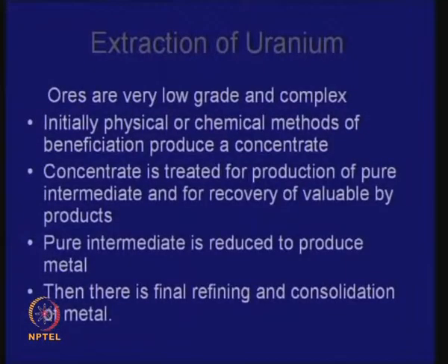We have discussed some methods for that. It could be vacuum arc melting. Essentially, if we remelt it under vacuum, ensure that all gases are removed, and once we make a consolidated metal in bulk form, its surface area would be low. So, the chances of reoxidation would be low. So, please remember, these are the standard steps we will need in the case of most of them.